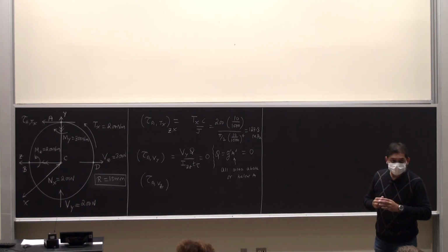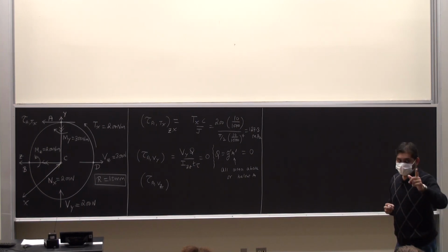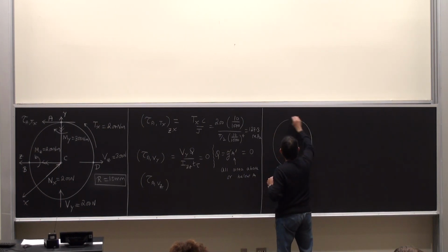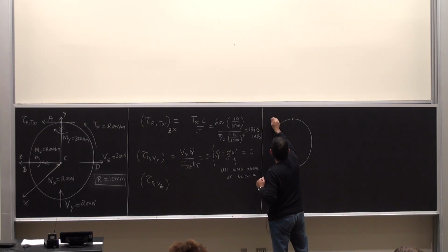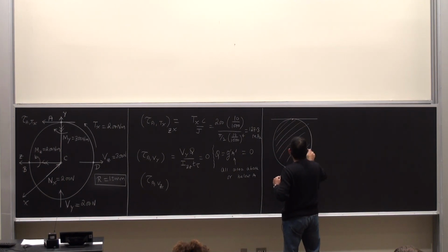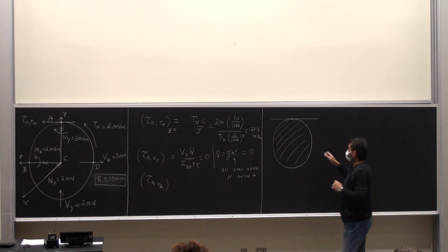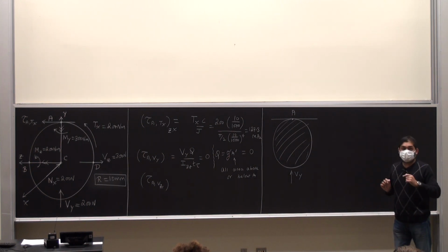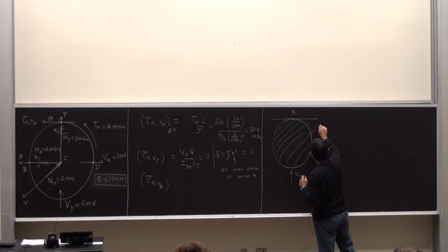If you took the area below for Q, then what would make it 0? Fantastic question. Let's say that this is the point A. Here is the shear force, Vy. Now, according to the definition of Q, this is my A prime.